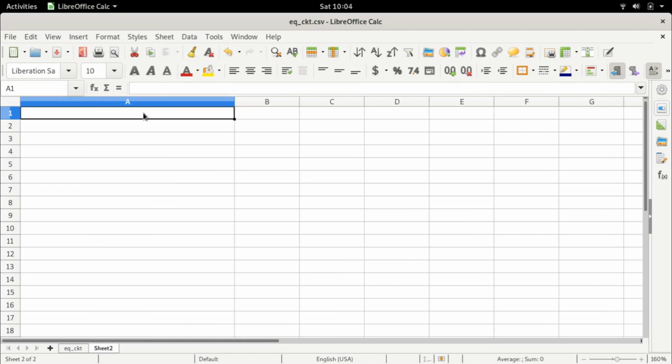So what we say is we are applying a voltage, right? So we are applying, just write AC voltage. We are applying an AC voltage of some frequency F, and this frequency F is in Hertz. Because of this frequency F, this results in, you can say, a flux which is rotating. Now, for now, let us consider a very simple induction motor which has only two poles, right? So which means you can have a multi-pole induction motor, but for now, let's say the number of poles is equal to 2.